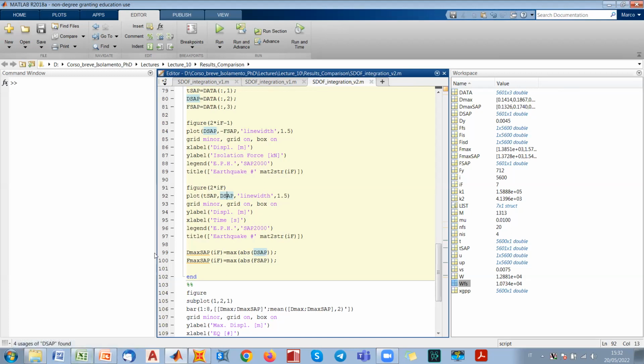So obviously you're not asked to run analysis through SAP2000 rather than simulations with a single degree of freedom, but you are just asked to provide the drawing of the force displacement loops of the single device according to design, and also of the whole isolation system. So it means that whenever you have rubber bearings or lead rubber bearings, for the total system, we have to sum up what we are expecting for the response of flat sliders and the total force associated to isolators.